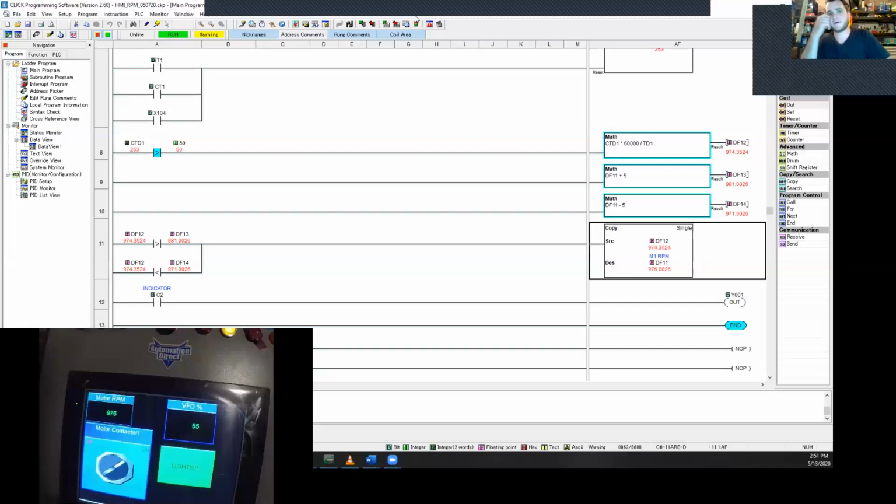But it's basically complicated math for how you use the controller to get something like this motor to spin at the exact speed you want, right? And so the whole point of creating this RPM counter is actually to work towards using a PID controller. We're going to take this input RPM value that we're physically measuring, and use that to tune and change our output continuously until we get the motor spinning at the exact RPM we want.